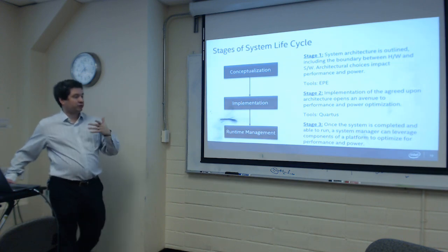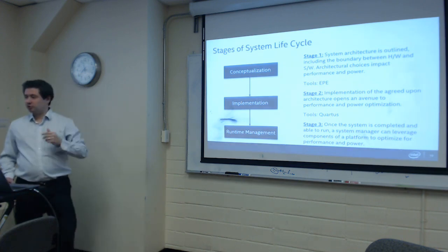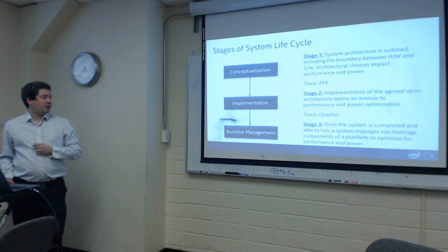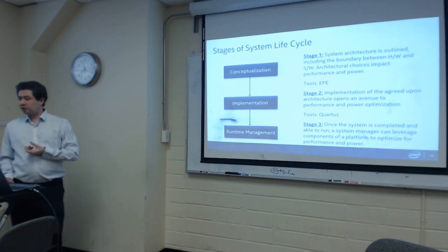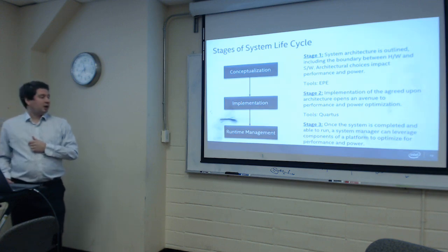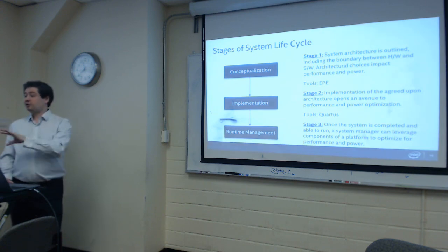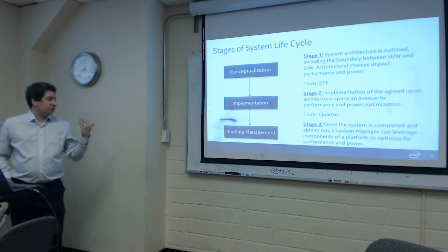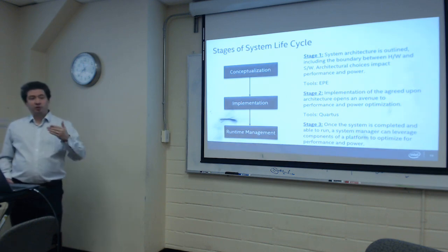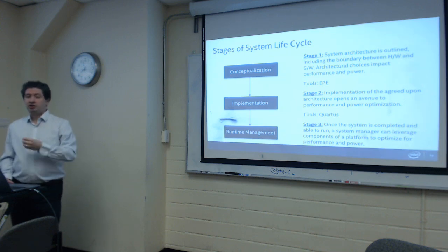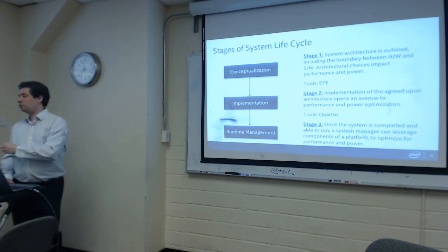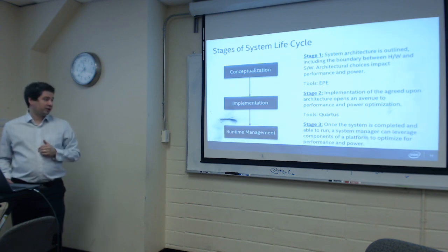So here's where we have a tool called Quartus that basically allows you to do what I described in the previous slide. Finally, at the very end, you've got the runtime management. So that's a reasonably unexplored area, at least for FPGAs, where what you're really looking at is managing the amount of power and the performance of your system when it is actually on the board. Knowing things such as when the design is actually running versus when it's not running enables you to decide, do I or do I not want to spend power on that particular space.